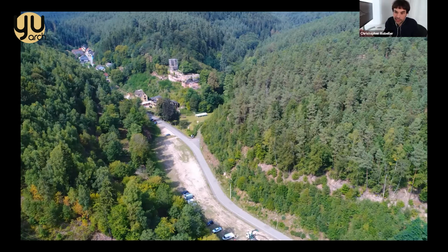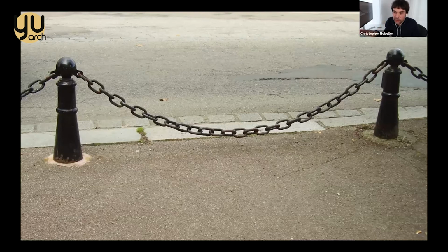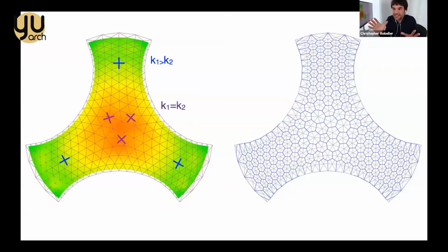We wanted to make it a little bit bigger, which brings us into the challenges of building a real shell. If you build a real shell, then you will not have a constant curvature. You will have a catenary shaped curvature, which is the shape that will not have any bending in it. And that's what we want for the joints. But the challenge that comes from that, and that's quite interesting, is that your structural optimization makes your geometrical or fabrication optimization a lot more difficult. If you want to make these planar shapes, then constant curvature makes your life a lot easier. If you have a curvature which is changing, and it's also, as you can see here where it's getting green, directional, this means you have in one direction of the surface a different curvature than in the other. Then your pattern needs to follow this direction.